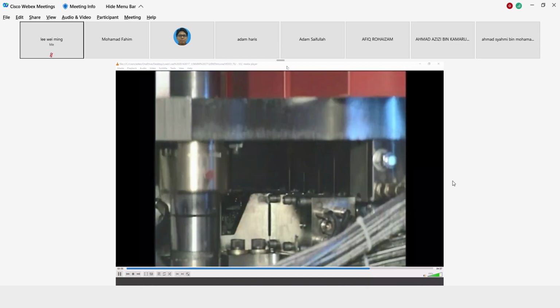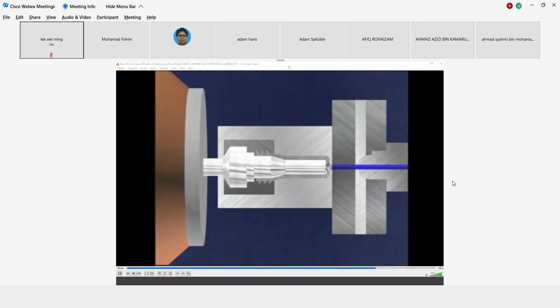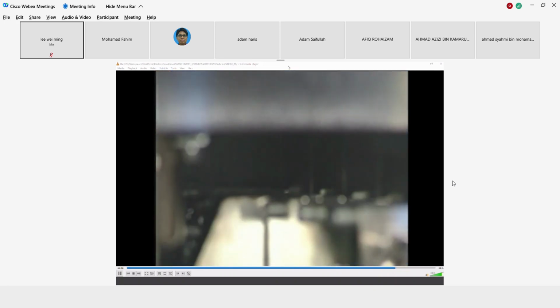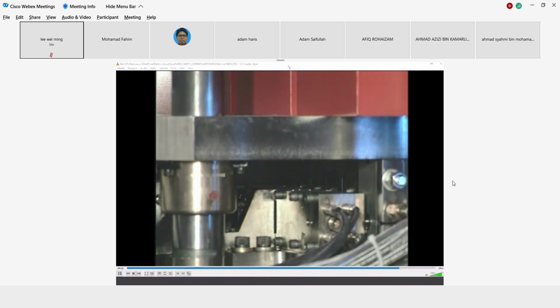The injection station is basically an injection molding machine. A ram, usually a reciprocating screw, forces the melted thermoplastic resin under pressure onto a metal core rod held within a closed, split parison cavity injection mold. After the outside skin of the parison has set, the parison mold opens, and the core rod carrying the parison rotates to the blow station.